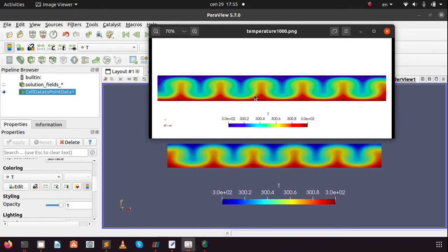But probably this is because we have a really coarse mesh, and this is something that happens also in high order codes. I was reading an article about the Rayleigh-Bénard case for the spectral element code Nek5000 by Paul Fischer, and he said that the number of rolls was very sensitive to the order of the spectral elements he was using. So he set an order of 7 in one case, so he would get the proper number of rolls.